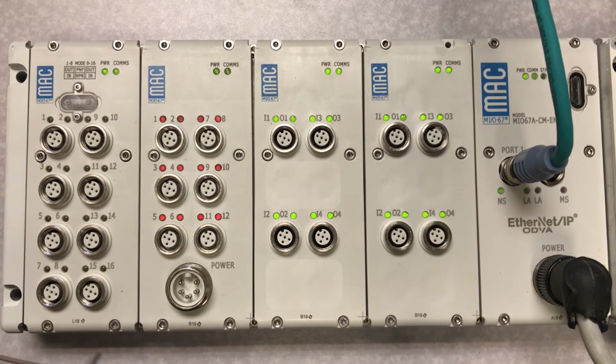The last module is a digital I/O module. It is comprised of 8 ports. Each of the ports has 2 inputs. Users can have 2 sensors connected to one port, such as an extended or retracted prox on an air cylinder.